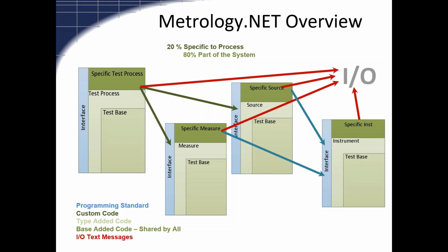So that's how the actor paradigm runs: when we want a source volts DC out of our calibrator, we're just going to tell it source volts DC, and it's going to generate that DC voltage, and then it's going to turn itself off. But we never have direct binding to each one of these objects.